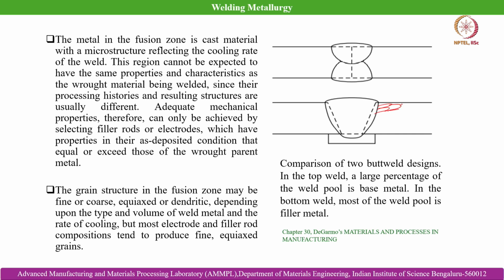Okay. So, this can be understood from, say, assume that this is a cold worked metal, and we have an elongated grain structure in this cold worked workpiece, in both the plates which are being joined with each other. The moment we try to get fusion welding between the two, this structure gets lost, and we generate a melt pool which solidifies with a much higher cooling rate.